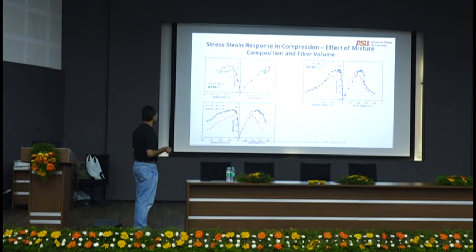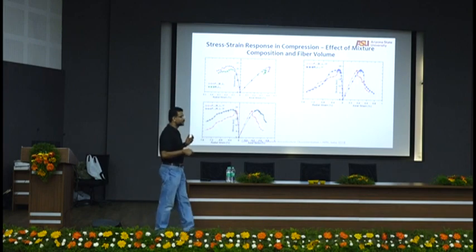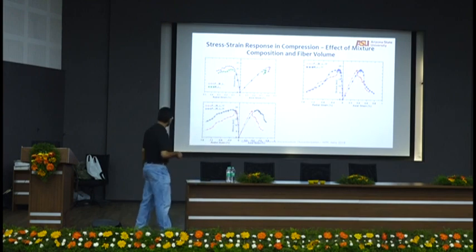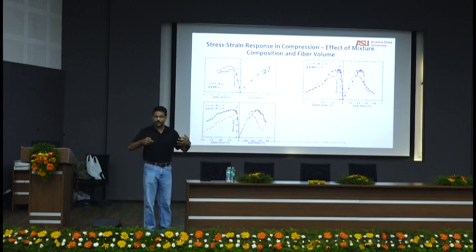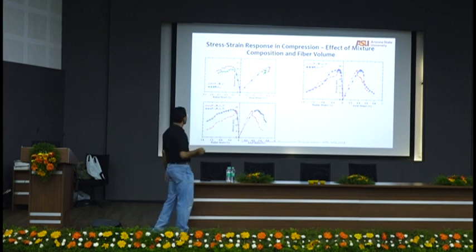Now if I put in 1% fibers, the story completely changes. Look at how the axis here, instead of 0.5, gets up to 1. You see the post-peak behavior in compression and the post-peak radial behavior in compression. So with fibers you get extremely high ductility. Look at 1% radial strain, 1.2% radial strain, which means you're letting your Poisson effect take effect so much without breaking the specimen. The fibers are holding it so that you can take much higher load.